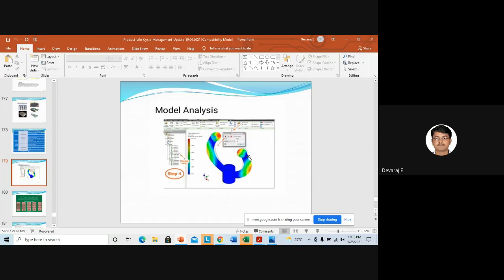If the first frequency of the external force is 60 hertz, and it matches, that indicates the material is going to fail once it reaches this force. Once you apply a force like 50 Newton or 70 Newton, and the external frequency matches the natural frequency, immediately there will be huge vibrations. There is huge displacement at that particular point, and finally the material will get fractured. Wherever you get red, you can see here, there is a red point. In this region there will be huge vibration, so finally the material will get fractured. So this is nothing but modal analysis.